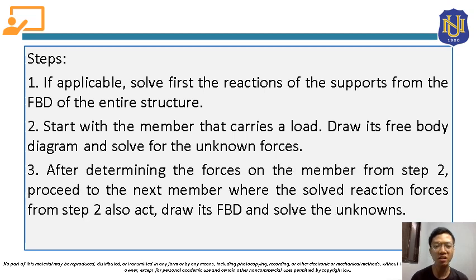Okay, so for number 3, after determining the forces on the member from step 2, proceed to the next member where the solved reaction forces from step 2 also act. Draw its free body diagram and solve the unknown.